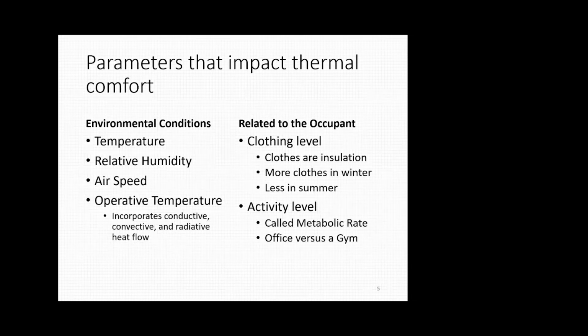Another thing that affects thermal comfort is airspeed. So air is a gas, right? And it has energy in it. If warm air is blowing over you and it's warmer than your body, it's going to be dumping energy into your body, right? If cold air is flowing over you and it's colder than your body, then you're going to lose energy. So the faster or slower that air moves over you, the faster or slower it transfers energy. So airspeed is another thing that plays a big part in that.